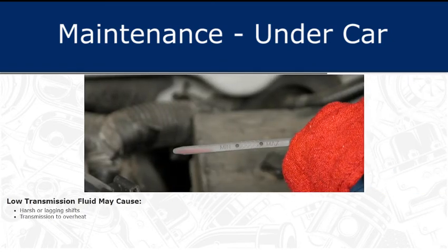All transmissions rely on fluid to function properly. If your customer has a concern regarding harsh or lagging shifts, the transmission fluid may be low. A low fluid level can cause the transmission to overheat.